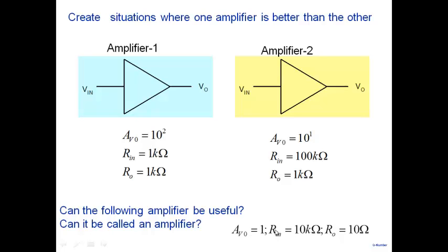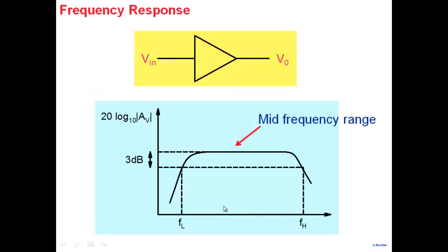It has a gain of 1. Now, gain of 1 means what? We are saying V0 equal to Vin. Is it not the same as a wire? A simple wire is also V0 equal to Vin. Right? So why do I use an amplifier? Just connect a wire. Wire will give me V0 equal to Vin. Alright? So is that a useful entity at all or not? Think about it. See how, if you're given something like this, you can use it to your advantage. Okay? Alright, so I'll leave you with those questions.